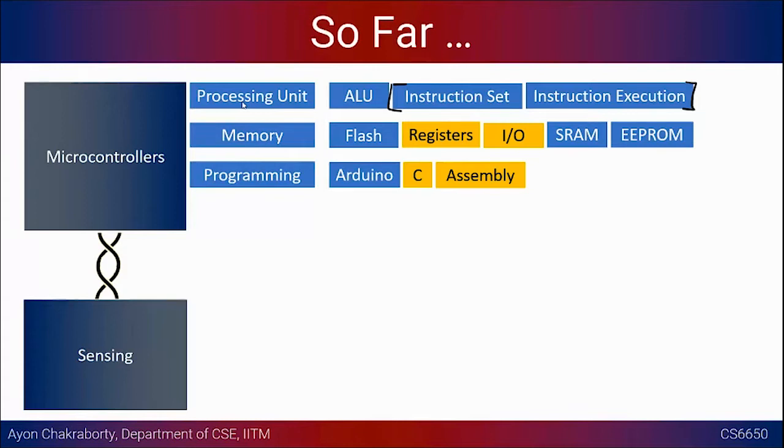Let's say in this case it is AVR, so you have to use some AVR specific header files. Or you can also use an assembly level program. Even in the sketch, I showed you how you can combine regular C statements with assembly level code, which is going to reduce your program memory size, or make it more efficient in terms of execution speed and so on.